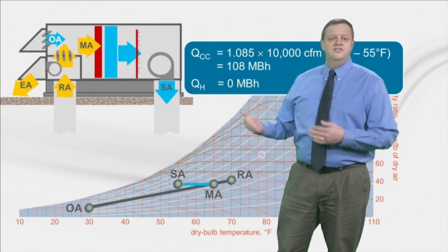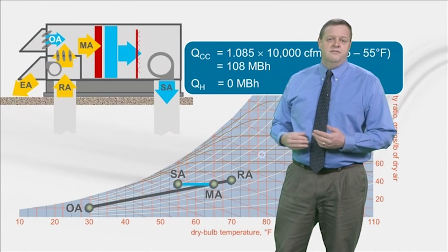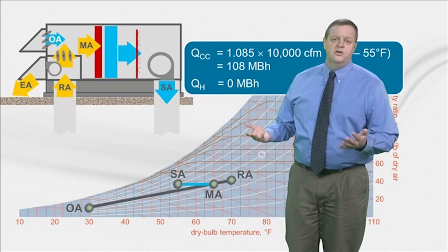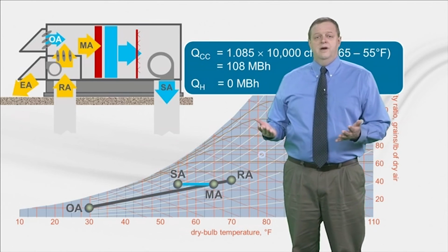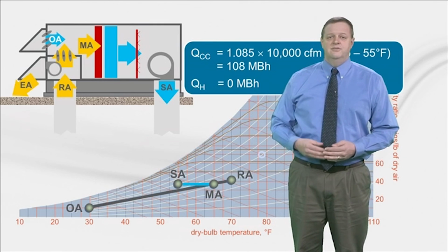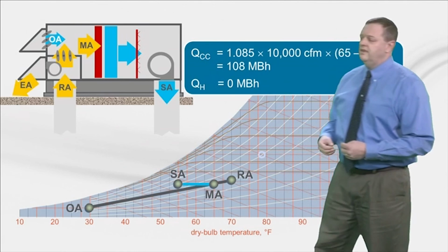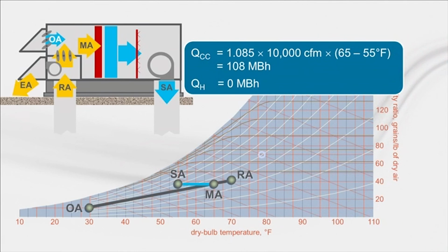Of course, this is just one snapshot in time to explain this trade-off. For many applications that require elevated indoor humidity during cold weather, a water-side economizer would likely be a better choice since it will not have any adverse effect on humidification loads. And again, ASHRAE 90.1 does have an exception to the economizer requirement for certain areas of healthcare facilities and other spaces where humidification is required for process needs.